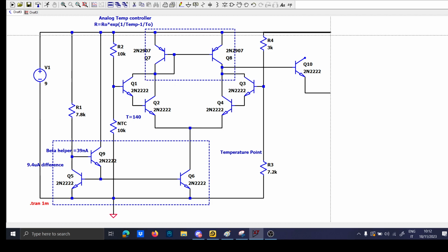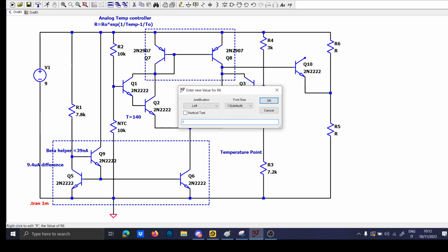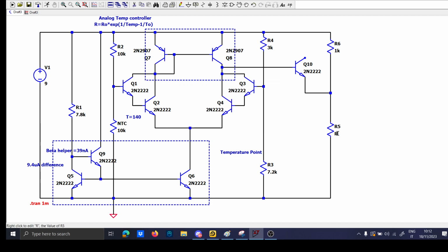If you put a divider on the emitter, you always have to respect the condition that the VBE voltage is higher than 0.7, and so with an emitter divider, you can program when this transistor will turn on. This is the basic idea of a transistor Schmitt trigger. Probably you never saw it, but I saw it in The Art of Electronics, and it works. I am quite surprised that it actually works.